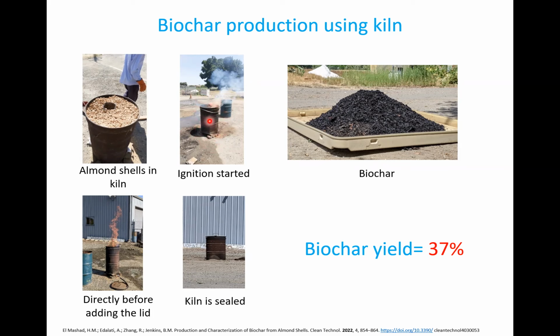Of course, you can't control the temperature in this case, but you can wait for maybe 30 minutes until the top layer of biomass started to heat up. The system is still open. After ignition, you will have to wait again 30 minutes, and then you have to insulate it, because pyrolysis is anaerobic, so there is no oxygen in this case.